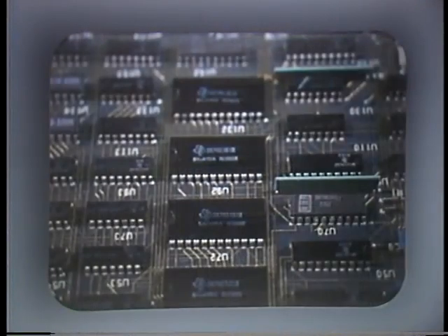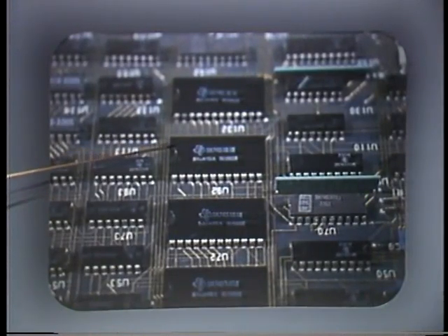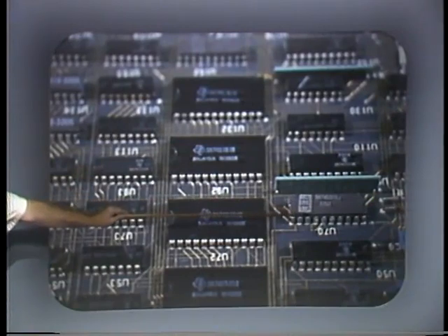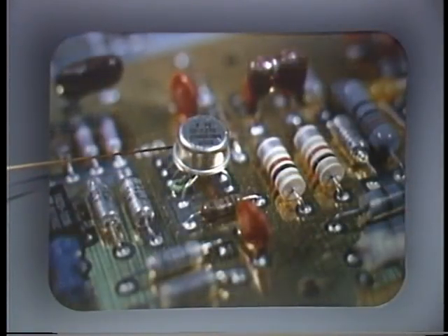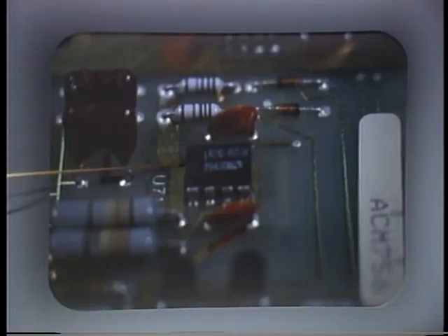Another class of parts which is easily damaged by static are the integrated circuits. Here are examples of small-scale and large-scale epoxy packages, ceramic packages, metal cans. Often these are the ones for linear ICs, and small 8-leaded dual inline packages. All of these components contain very thin oxide layers, and this is what is most commonly damaged.